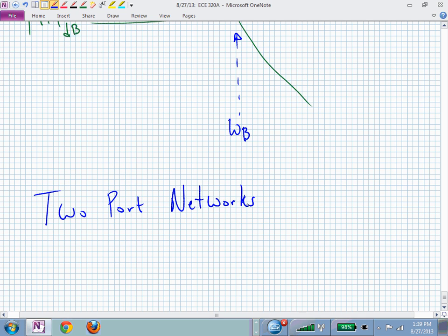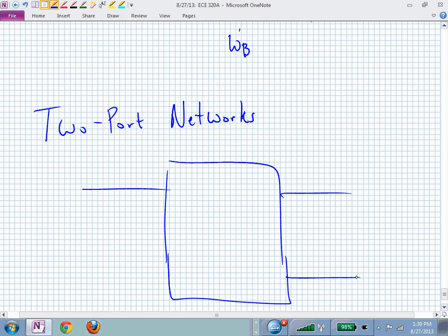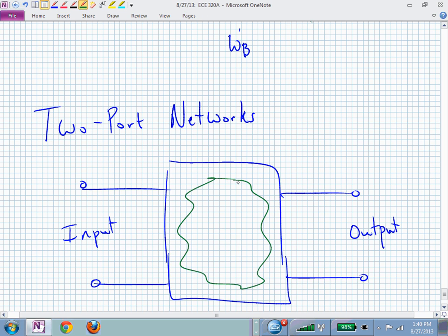into more generic circuits, which are two-port networks. Now we're looking at saying, you know what? There's a bunch going on in here, but if you just tell me what happens at these two ports, the input port and the output port, if you could parameterize what's going on here, maybe this is 200 transistors and some capacitors and probably not inductors and some resistors.